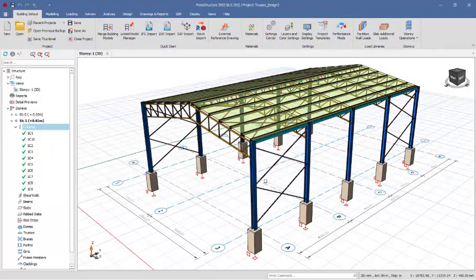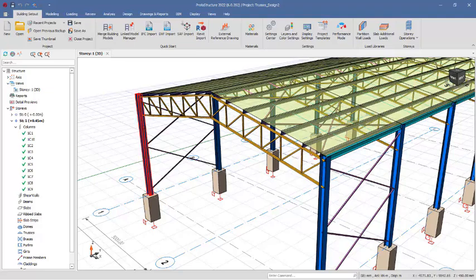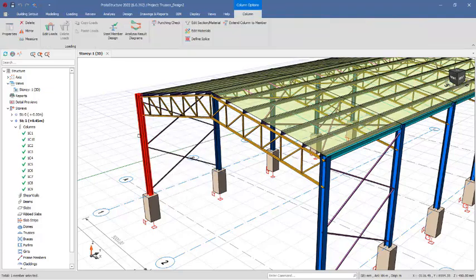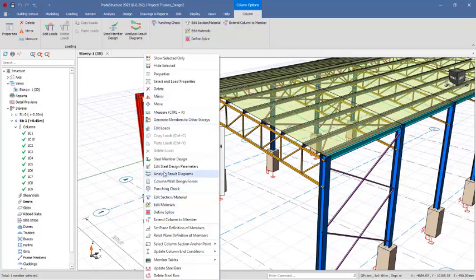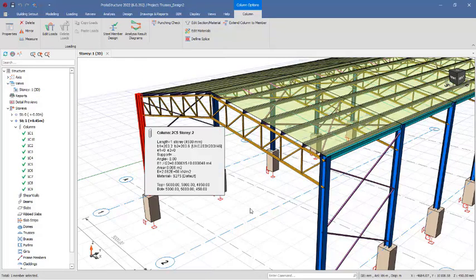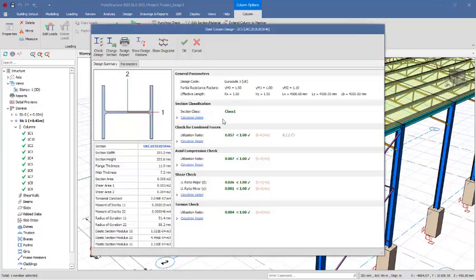Close this dialog. We want to check the steel stanchion to see if it is actually designed. So you get it selected. Alright, you right click and then click on the steel member design right there. So this will open up a dialog that we will be able to use to check and confirm that the steel stanchion has passed design, as you can see, and the U ratio you can see is very far from 1. That simply means you can reduce the sections of this steel stanchion successfully, and it will still be able to carry the structure. So click on the OK options.